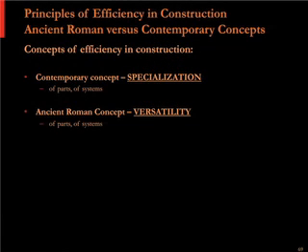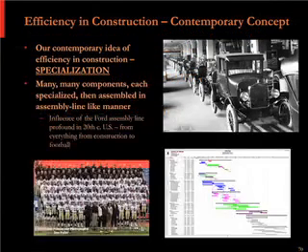So structurally what that means is the deck doesn't brace these members in any way. And so the members would be prone to buckling if they were like this. But by using them on the flat, they can't buckle. So there's actually a structural logic to what they did here that doesn't necessarily meet the eye. So it's just to the point that you need to really look at it closely and understand it, and don't just assume you know better.